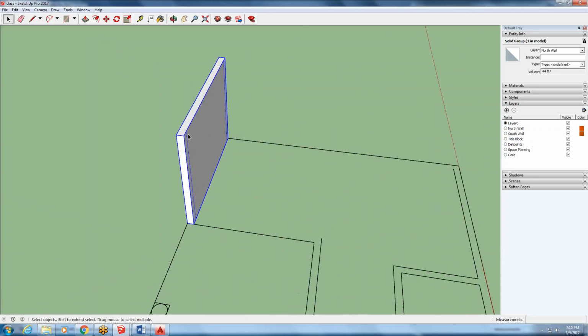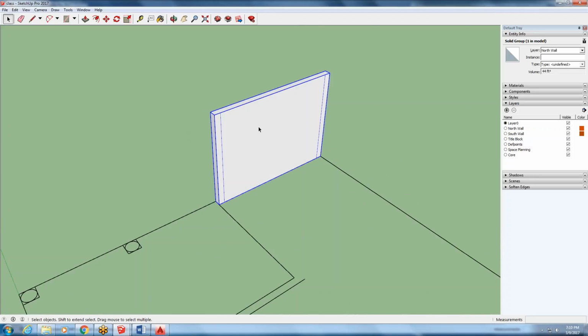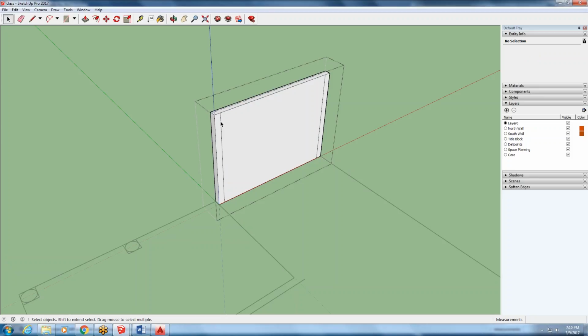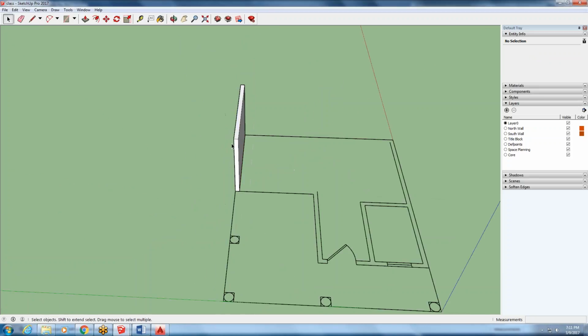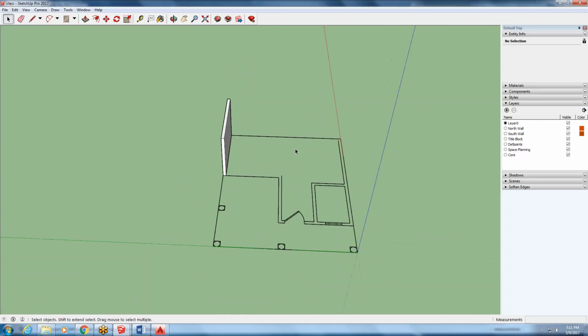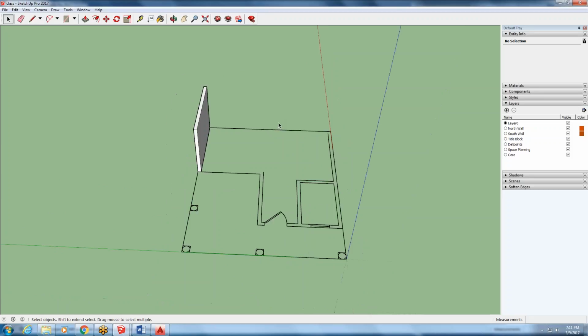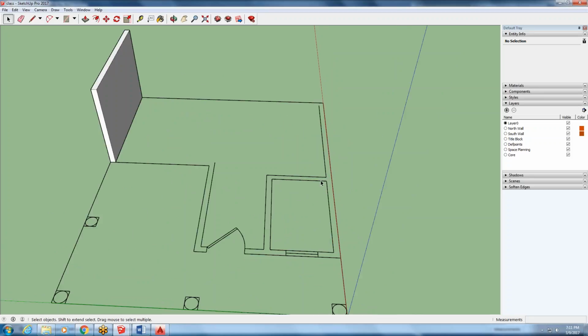Okay, then notice because I had to create those cut lines, if I double click in, there's like these messy lines. Because it's a whole face and everything's good, I can just delete those out and my face stays intact. Okay, so then I can come out by single clicking and I'm back into my model. So now I'm going to create this bigger wall over here, and I have enough references by deleting these out that it shouldn't hurt anything.